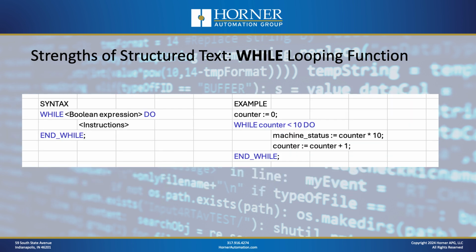Correct. Unlike the while function, which is powerful, but if you're not careful with what you're doing while you're in the while, and you don't create a condition to get you out of the while, you'll be stuck there. But the while statement still has its purposes, and you just have to remember to sooner or later hit the while condition to turn it off. Right. And if you set up a while condition which is dependent on, let's say, a physical input, you're never going to meet that while condition because it's never going to go check the status of the input. It's going to be stuck in that while loop until it watchdogs.